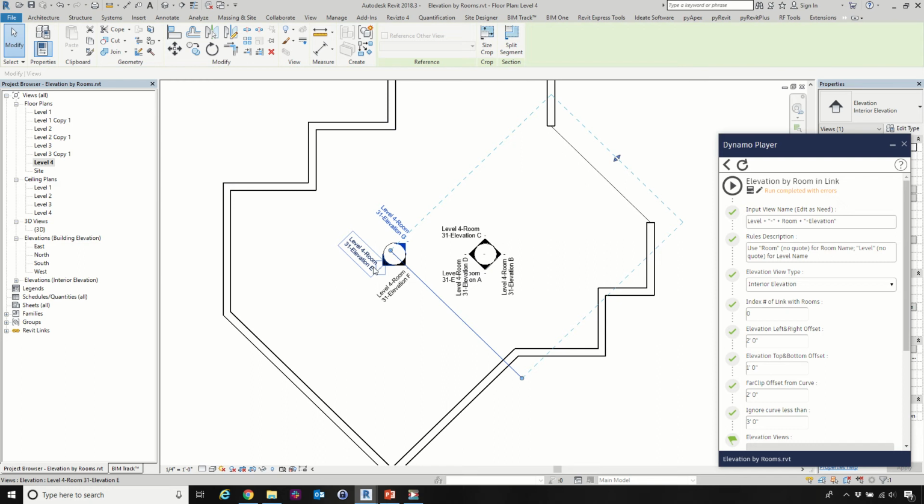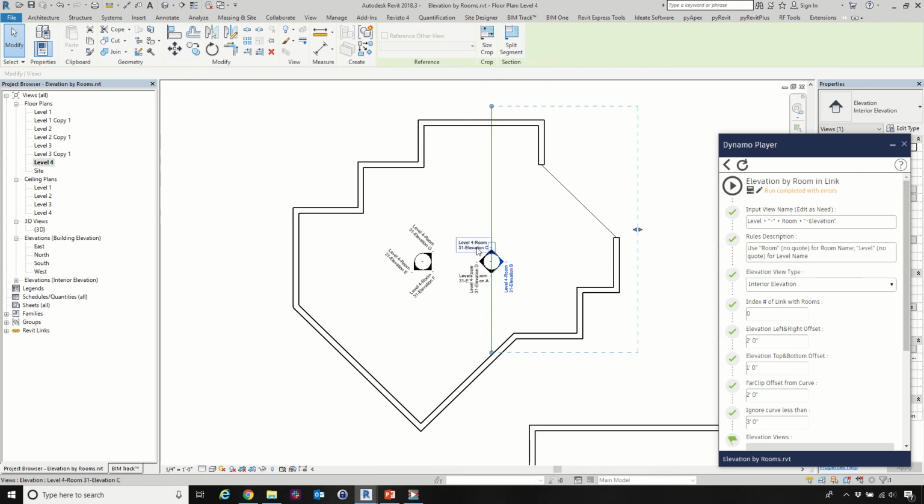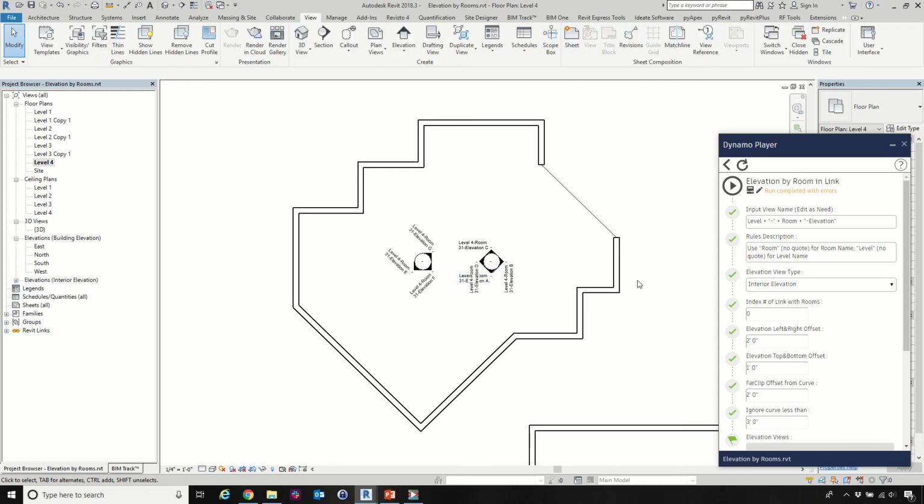You get one elevation marker with 3 views, and the other elevation marker with 4 views, where this one is looking at 1, 2, 3, and it's 2 feet to the furthest line of the furthest wall. This one is looking at 1, 2, 3 wall. It's 2 feet beyond the furthest elevation. And similar over here, it's looking at 1, 2. So on and so forth.